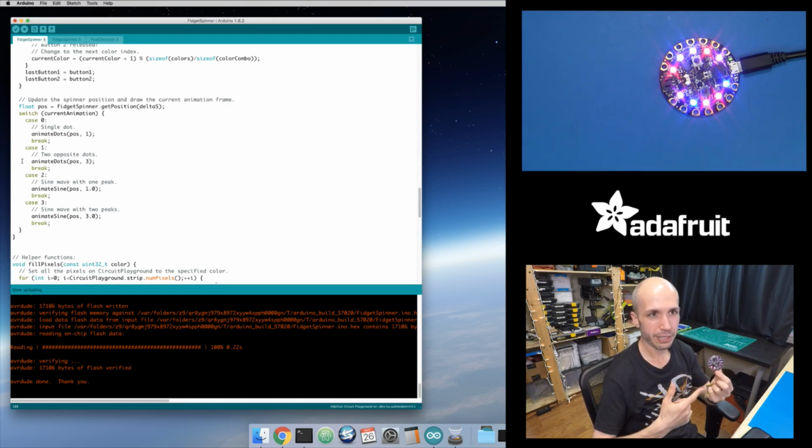This is just demonstrating some of the neat things that you can do with the accelerometer on Circuit Playground. The accelerometer detects force, so it's useful for detecting things like gravity, but it can also detect a very big force, like me flicking something or touching something or really shocking that system. But the tricky thing is, how do you detect a strong, instantaneous force like that, while ignoring this slower motion, this less intense but constant force?